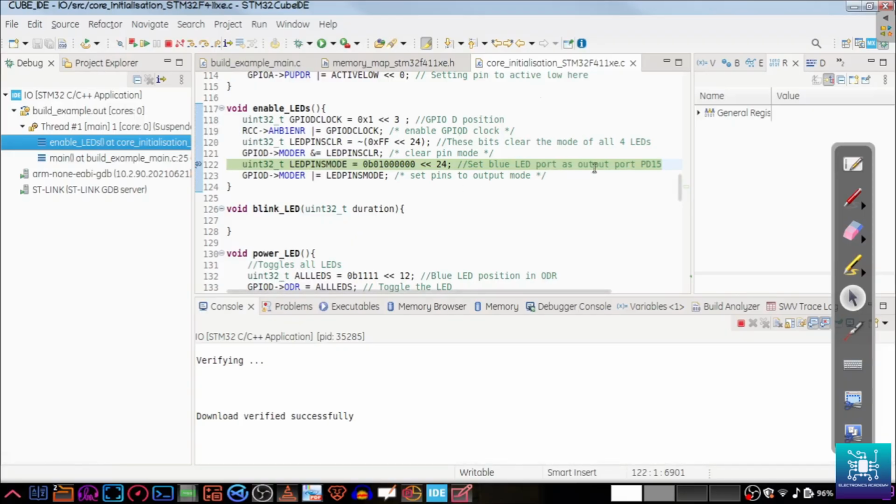Okay, because as we discussed in the beginning, we have to set the blue LED first, and then the LED actually moves from blue LED goes off and it moves clockwise and goes around and comes back to the blue LED at every press of the user button.